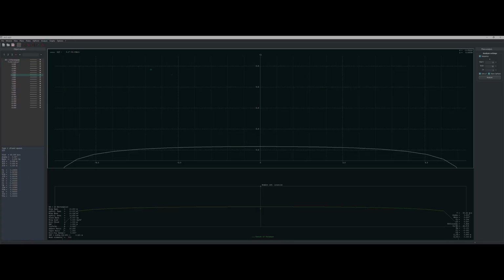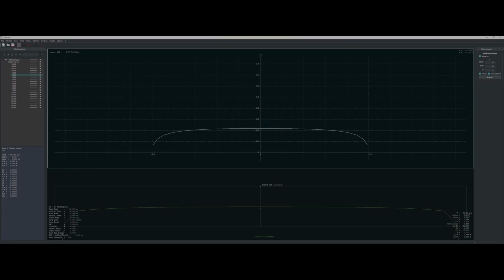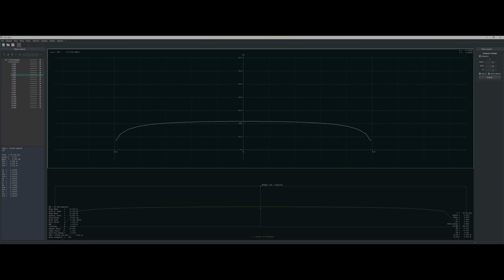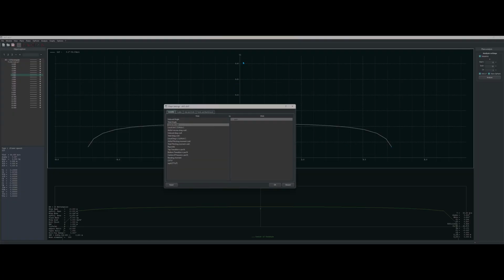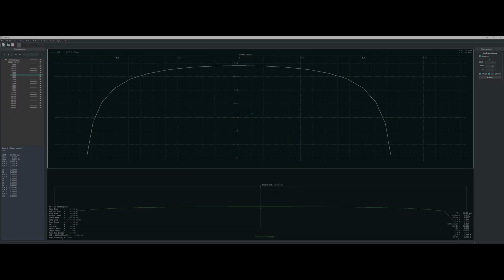And now if we go in here, this is where we get our span-wise parameters. We get our parameters along the span. So right now we have CL over the span of the wing, which would end at 5 right here. And if we double click local lift coefficient, we could also check induced angle right here.